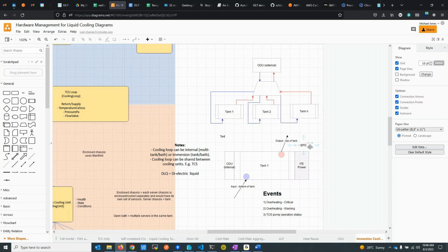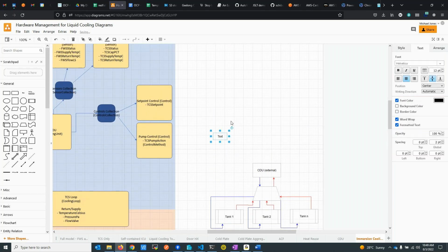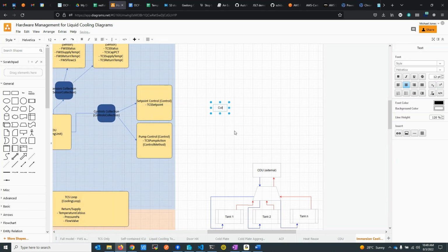So generally speaking, we've gone through a bunch of experiments where we boil coolant within cold plates and so forth, and exactly right, it gets pretty gnarly because the glycol has a different boiling point. So then your water vapor transmission losses increase, the viscosity of your coolant massively increases, and then you end up fouling any form of thin geometry within the cold plate itself.